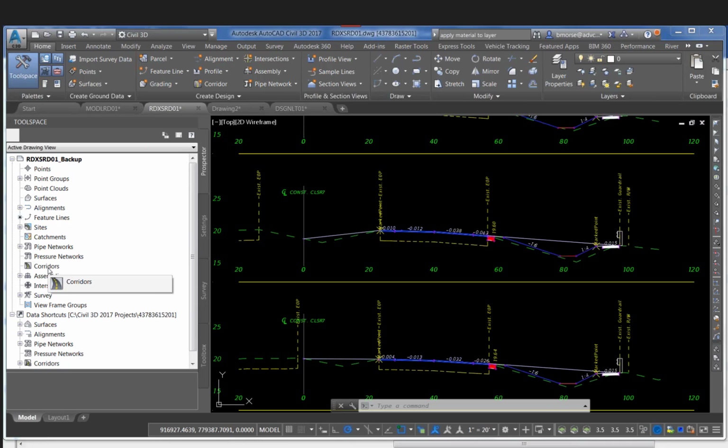The corridor model is being sampled as an XREF. So not a data reference, but an external reference. And so you can derive your cross-sections just from sampling through an XREF. And what does that do to the code set style? Well, it just gives you some limitations on how you can apply that code set. If there's no corridor model, how would you apply the code set?